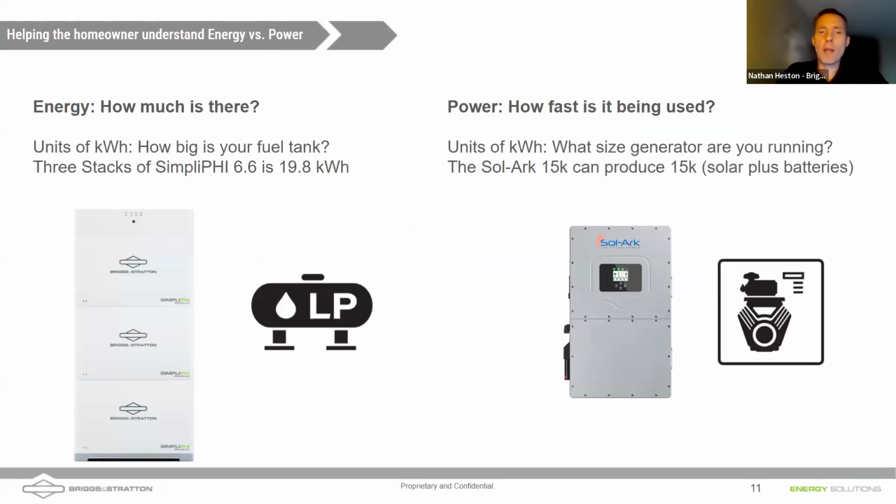One of the things to compare when we're looking at generators versus batteries, and we're going to talk about generators plus batteries here in a minute, is what essentially is a battery in the generator world. So if you're used to a fuel tank, like a propane tank, or maybe you just have a utility supply of natural gas to your home, essentially the batteries are a tank, right? But they are generally a smaller tank. You're looking at 20 kilowatt hours of energy stored in that tank. And if we're looking at a 100-pound propane tank, there's a lot more usable energy in that propane tank.